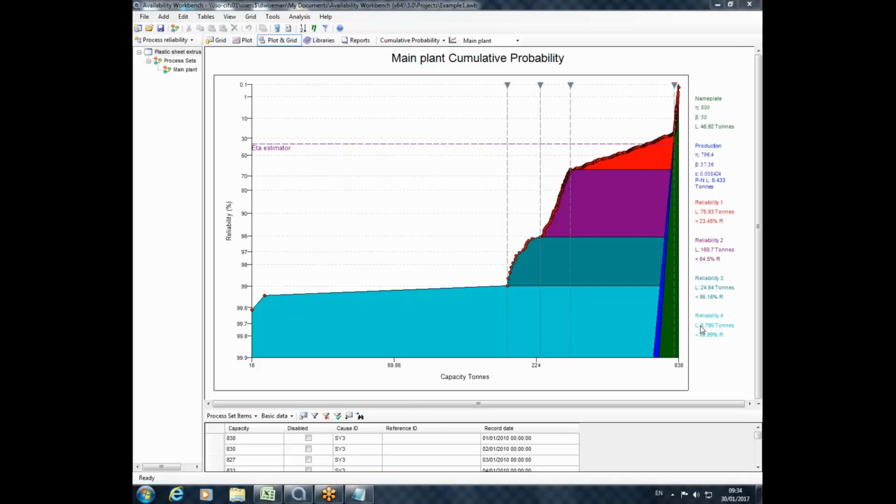Okay, so I'll answer very quickly the enterprise question first. The enterprise system is for project management. It allows you to store your project files in an SQL Server database and thus control access to them. So you can control access by individual users, by groups of users. You can also have version control of your project, so you can create new versions of your project every time one is checked out and checked back into the system. You can compare those versions of a project and see what the differences are, who made the change, when they made the change.